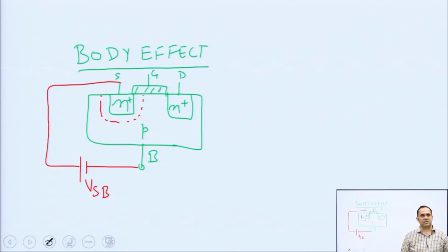This basically means that without making a lot of changes in the geometry or the doping concentrations, you have effectively increased the threshold voltage. Now you can design transistors with lower threshold, with lower delays and better power consumption, and still control the sub threshold current by controlling this body bias. Using this concept, we have two techniques, one is VT CMOS and another is MT CMOS.